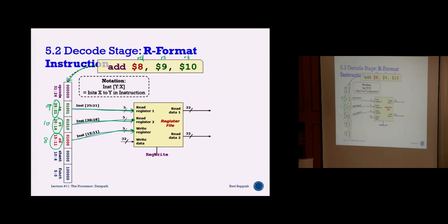See that if you look at it from half cycle, when the clock comes in, it's already the new value, correct? The PC value for it. And then your instruction that comes here, the IN here, is the next value, right? That means throughout this clock cycle, my PC already became 104. But then it doesn't do that. Why? Because this one is 104, which means that this one also becomes 108.